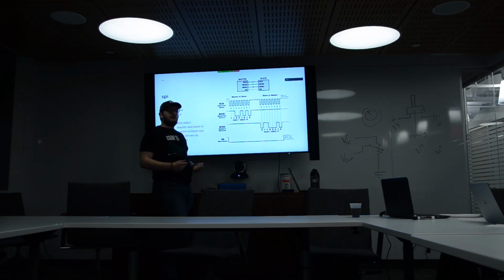But it's actually a sine wave, which is just modulated. No, this is not a sine wave. This is a square wave that is very clearly defined to have highs and lows. Granted, the signaling on the bus might have slight curves to it, but that's just because of parasitic capacitance. Internally, it doesn't care. It's just literally checking if it's high or low. High is a specific threshold, low is anything below that threshold. There's no analog magic going on there at all.